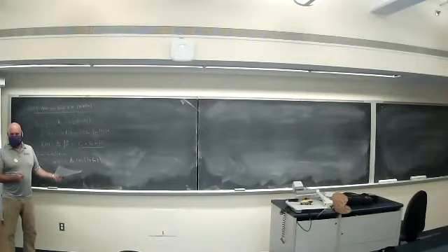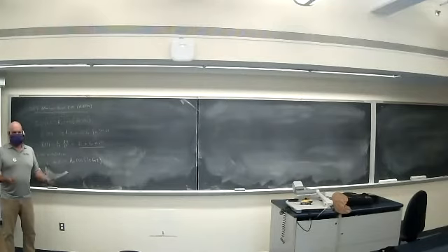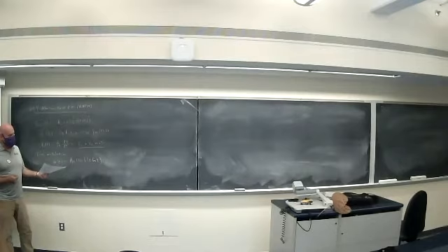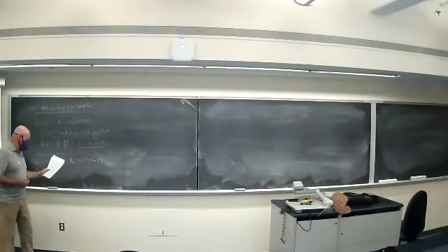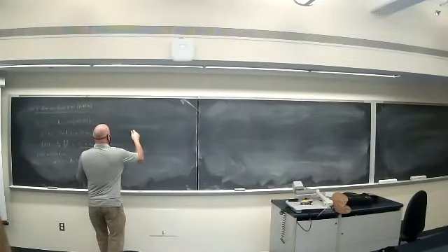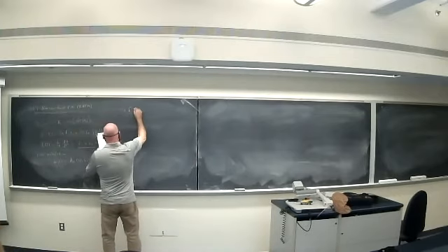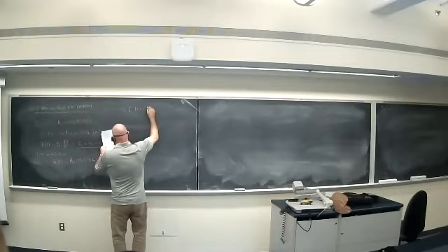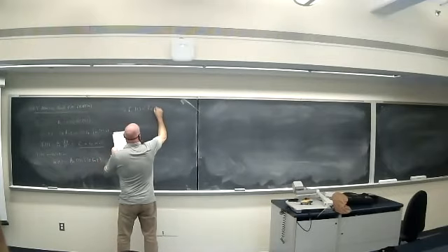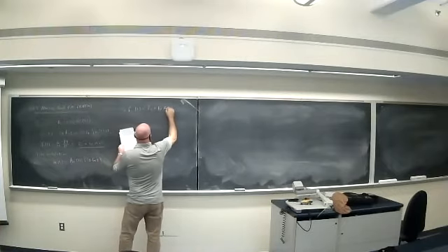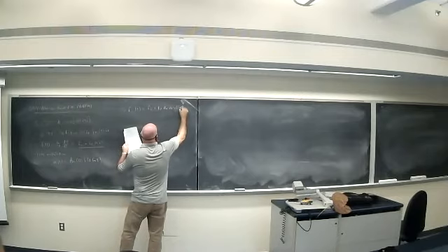We can have it with AM as well. We talked about the tone modulation case, but it is something that you can hear. It's a nice test signal in the lab or in the field, but it's also nice because we can deal with it theoretically and at least compare this to the bandwidth for AM. So the instantaneous frequency then is f_c plus k_f A_m cosine of 2 pi f_m t.